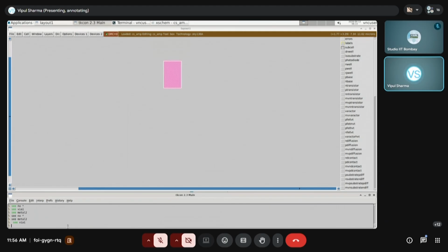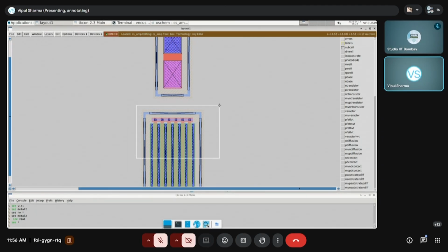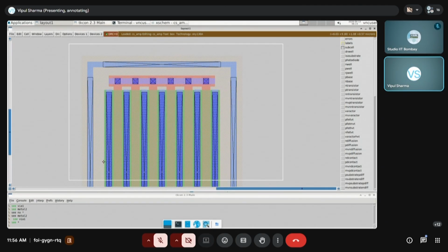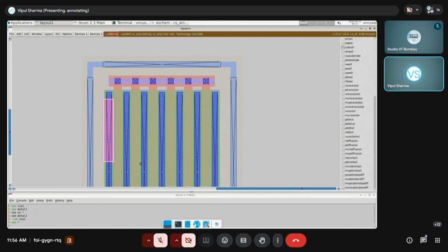So they both look pink, but these layers are available here. So now this is an additional layer which I have added. And similarly, I have to add these layers here also, or between these terminals. These are the drain terminals, alternate terminals of NMOS. So I will have to add via here, here also, because this connection has to be made using metal 2. So let me zoom in to this region. I will build a box and then use via 1. Similarly here,